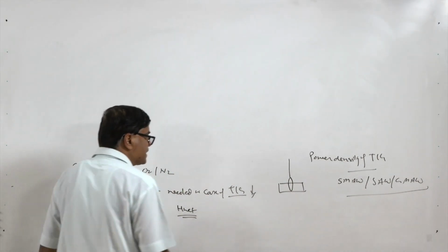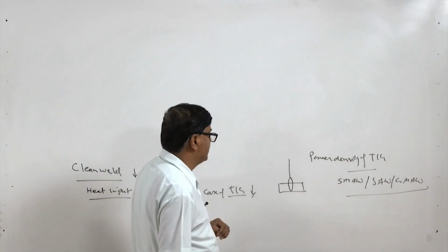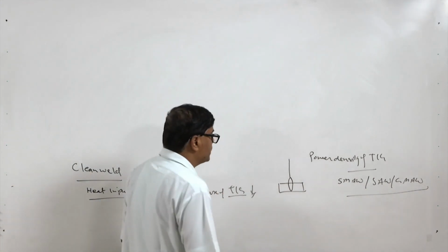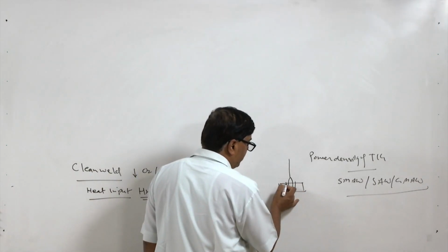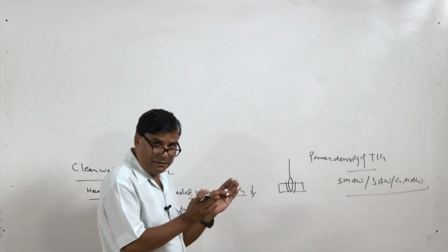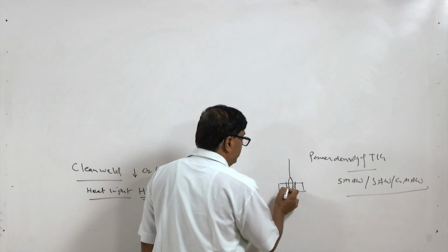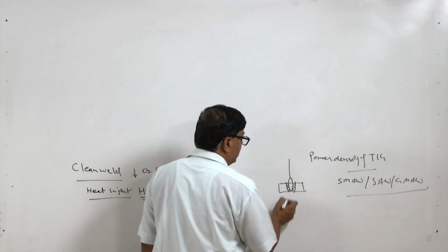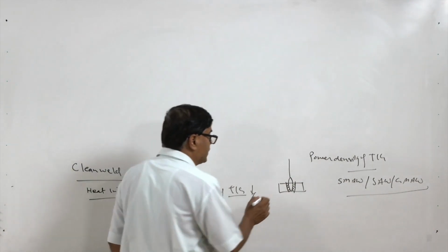If the H net is less, it facilitates melting even with the lesser heat input, and this goes in favor, because when heat input is less, the heat affected zone formed on both sides of the weld joint is limited, and the high cooling rate results in the finer grain structure in the weld.